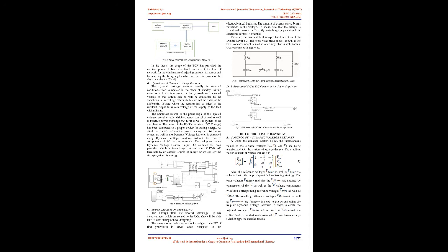Fig. 1 block diagram of the complete system. 2 modeling of the system. A dynamic voltage restorer. The DVR is a means for compensating short-term insufficiencies of power in sensitive loads. The ability of the DVR to compensate varies with the maximum injection voltage as well as the power capabilities during sag voltages. When continuous voltage drops occur, the dynamic voltage restorer, DVR, can compensate with a very operative approach such as the DVR algorithm. The algorithm reduces the real power delivery necessity. Though, its limitations on restoring the load current as well as the load voltage cause fluctuations in the phase angle. Fig. 2, block diagram for understanding the DVR.